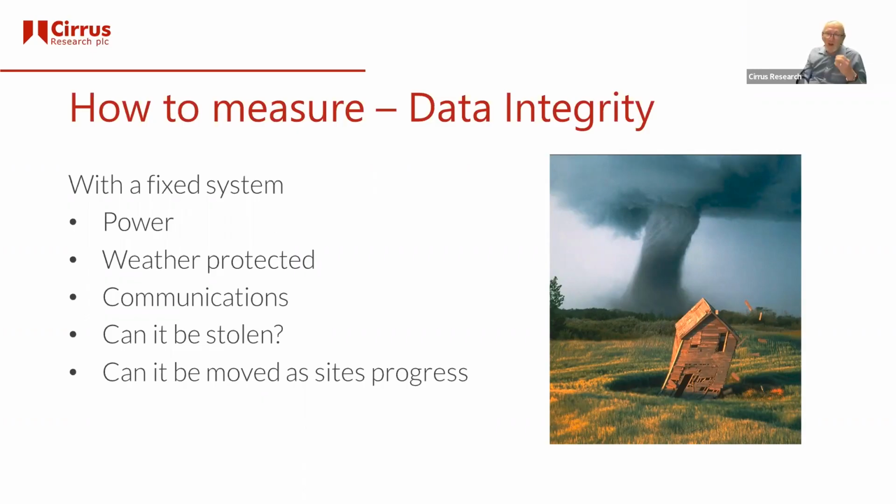But a few things for these unattended, fixed systems, which could be there for months. You need to think about power. Can you get a power supply to it of some kind? Is it going to need a solar panel? Can you get away with big batteries, that sort of thing? Because these things do take power. They won't just run on a couple of days' worth for 6 months. You need to think about power.